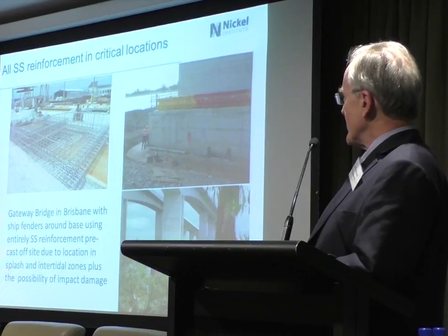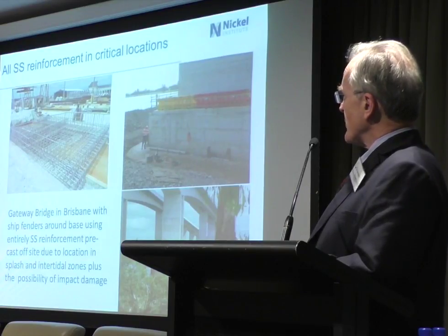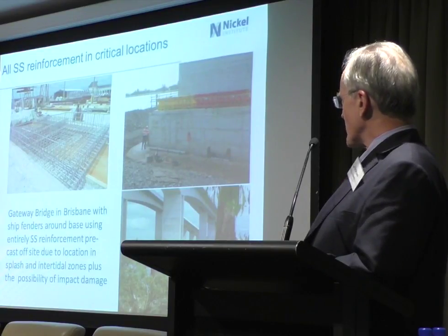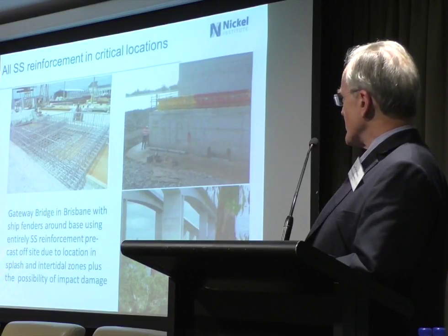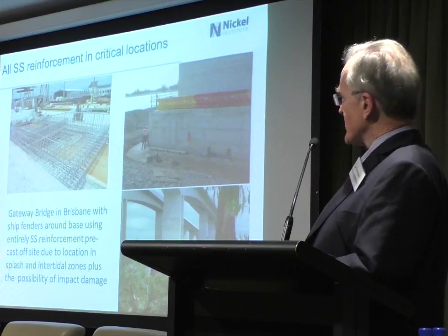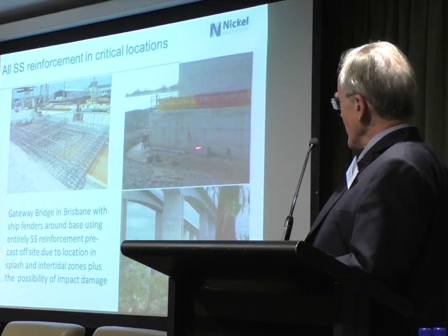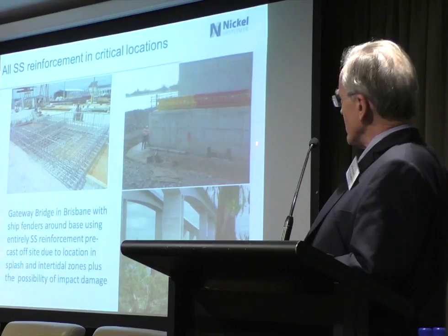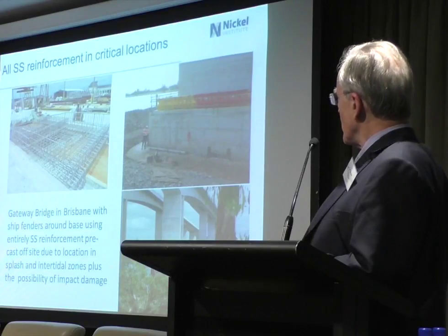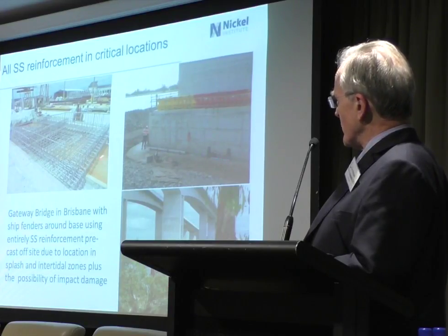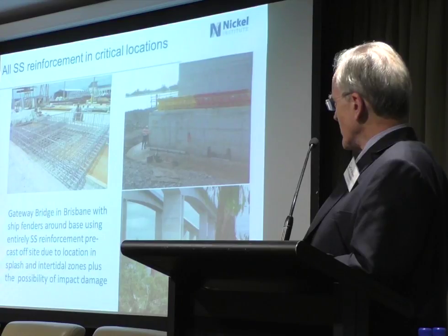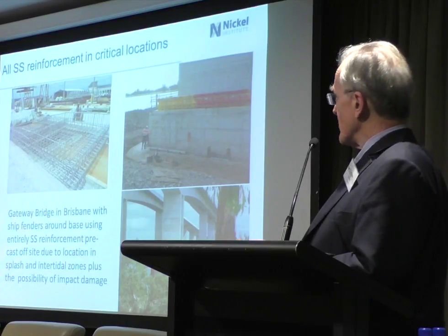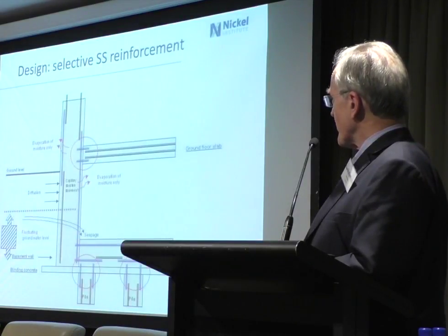Gateway Bridge. This is the bridge that has 3 times the design life of its companion bridge. And so they said, right, well, we've got to use lots of stainless steel because otherwise it won't last. So in this area here, down around the tidal zone or where it may get hit, the bottom of the piers, down the bottom here, it's all stainless steel reinforcement, absolutely, because of the possibility of getting chlorides in.